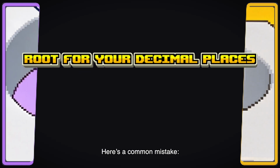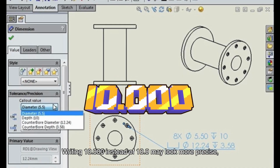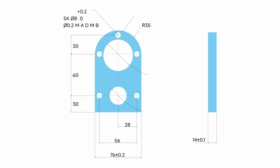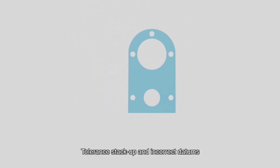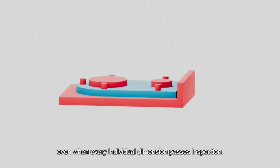Here's a common mistake. More decimal places don't automatically mean tighter tolerances. Writing 10.00 instead of 10.0 may look more precise, but the actual requirement comes from the tolerance callout. And dimensions don't work alone. Tolerance stack-up and incorrect datums can cause assembly problems, even when every individual dimension passes inspection.